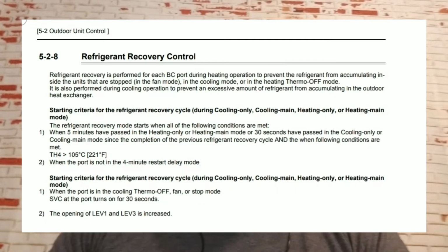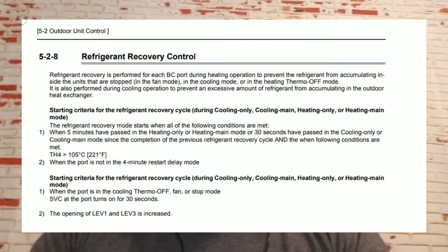Interestingly, if it runs hot long enough, it actually slips into a mode where it tries to recover liquid from the system. It thinks, well, maybe it's trapped inside in some idle line sets, and it will open valves and change its behavior for a minute to try and pull some of that back. So it's actively trying to move refrigerant around and correct itself. And there are times when that's all it really needed to do, and so you'll get this nuisance trip just every blue moon, just kind of a hiccup.